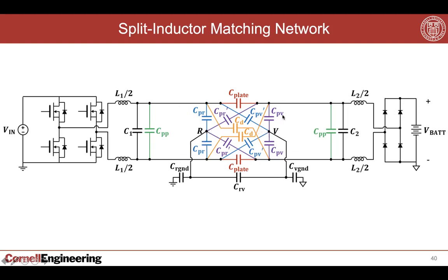Same thing with the vehicle. It basically sits between them, is at 0. And so what that does is basically put 0 volts here. This is 0, so it effectively nulls out this capacitance because you've got 0 volts across it. Same thing with this capacitance. It nulls it out, and a 0 from here to here also nulls out this capacitance.